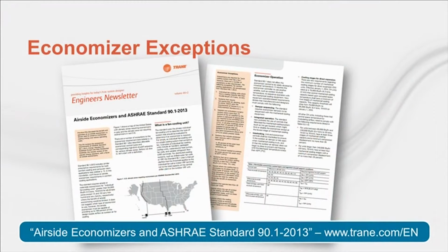There are a number of exceptions to exempt economizer usage. The 2013 version of 90.1 lists 10 exceptions, with some having multiple components. Some exceptions are specific to building or space types, such as hospitals and ambulatory surgery centers, supermarkets, and computer rooms. Other exceptions exempt economizers if condenser heat recovery is used, or if cooling equipment efficiency is increased by a climate zone specific threshold. Last year, we published an engineer's newsletter on economizers, and in it, I paraphrased the exceptions that apply to systems that serve comfort cooling applications. You can find a link to this newsletter online and in your bibliography.